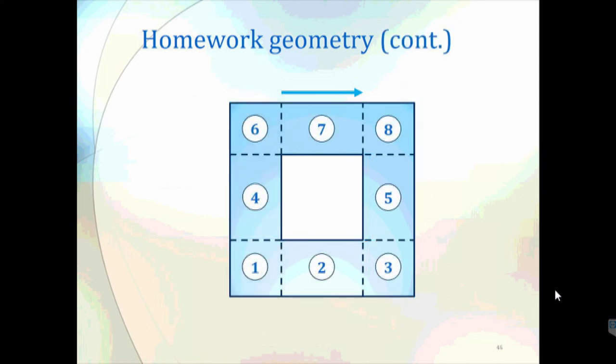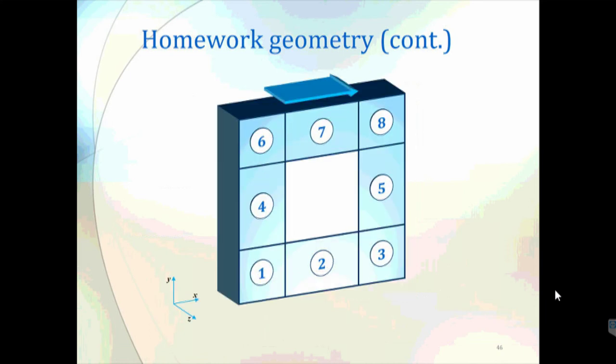and in order to do that, we'll have to divide our object into other blocks, and those blocks are listed here. I have numbered the blocks 1, 2, 3 until 8. But remember that each of these blocks is in 3D because OpenFOAM will not take 2D geometry. You will always have to specify 3D geometry. So basically each of these blocks is in 3 dimensions. So it is a cuboid.